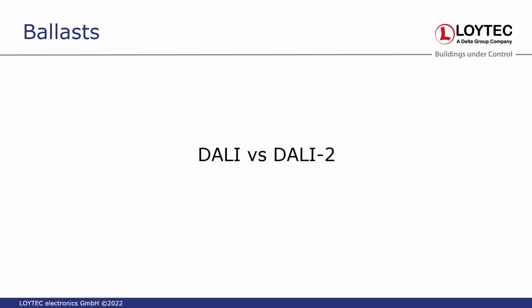What we have sometimes seen on some sites is that there are ballasts out there with some buggy firmware that are confused when suddenly DALI 2 frames appear on the same channel. Sometimes, with a certain content of the frame, they get confused and start acting in a strange way, or resetting or locking up or whatever.